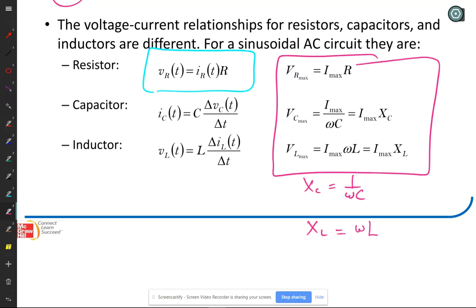The capacitor is two plates that don't touch each other. At low frequency, you have an open circuit. No current goes through. But at high frequency, you have the energy being stored and passed back and forth that makes it behave more like a wire. So we have the equivalent of Ohm's law using reactances.